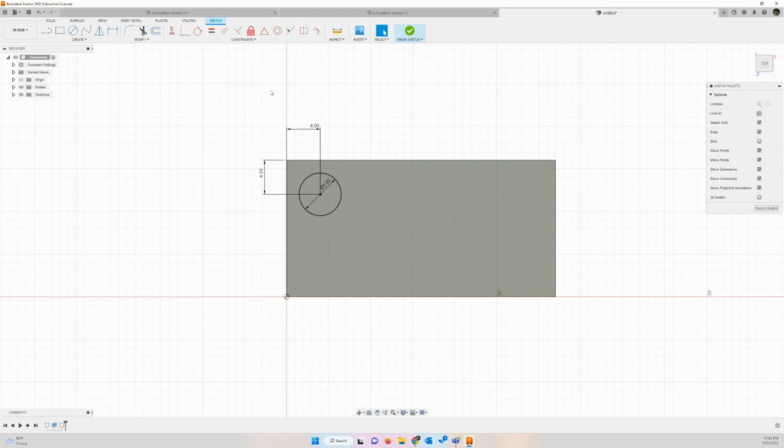Now, there is no way in this world that I want to go and draw 7 more circles for a Lego brick with 8 connectors on the top and position all of those. Let's start off with some parameters. My connectors, center point to center point, will always have a distance of 8 millimeters. Okay, I'm going to have 4 in a row. So 4 in a row, the rows running the length of the brick. And I'm going to have 2 rows of 4.